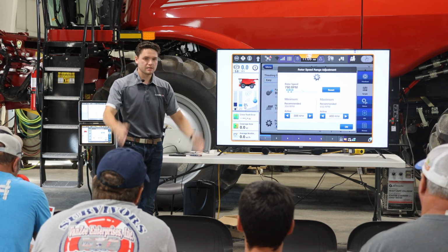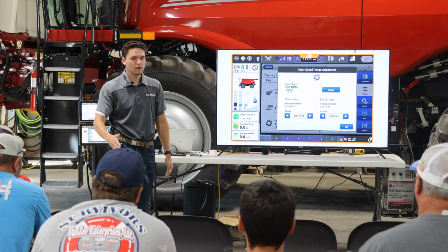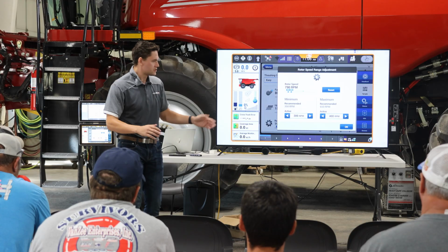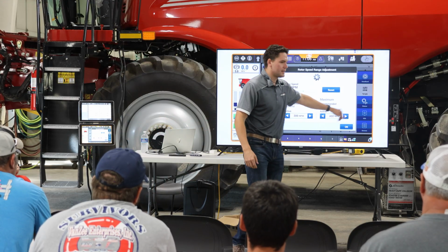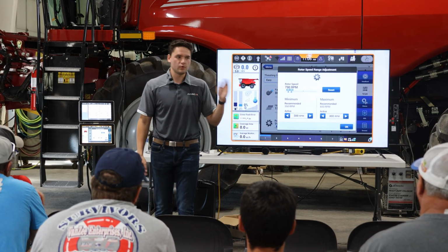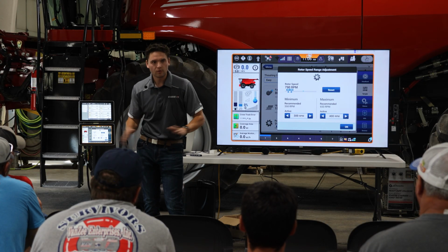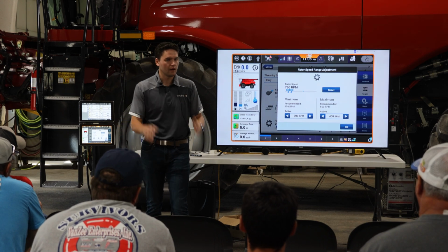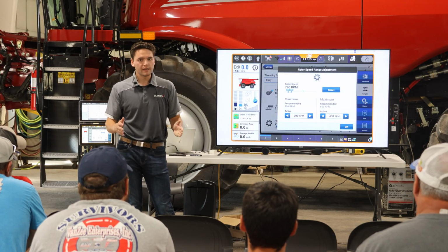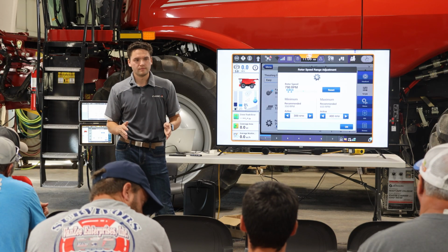And when I say guardrails, I'm not talking about cheap, flimsy ones that we could easily drive through. These are hard barriers. It will not go above 400 RPM. So if we want to say, and this is a soft line I want it to follow, keep in mind that if you put that to 400, it is at 400 for max. So if you have variability in the field where it might need to go up to that 450 on small pockets, it is no longer able to. So just keep that in mind. It will help stop it from overshooting or falling out of range sometimes, but you are limiting the test points automation can do to produce the outcome you want. Just keep that in mind.